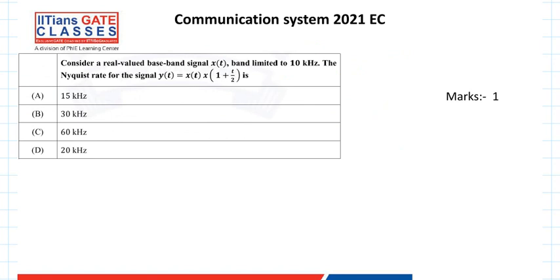from the Fourier transform. So first thing is that if you have any signal x(t), and let's say its bandwidth is a, okay, and let's say you have a new signal x(t by 2). So here you're doing the time scaling. If you do the time scaling, its bandwidth goes down by a factor of 2. So this is one of the properties that we have to use.